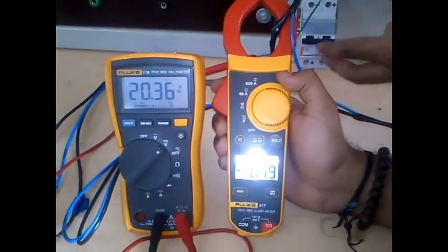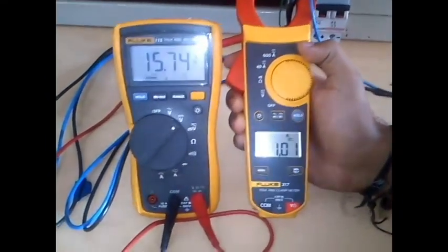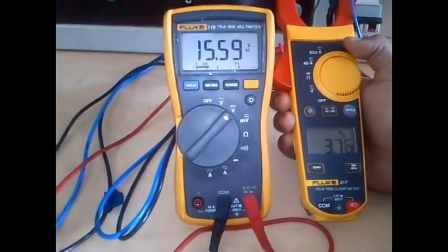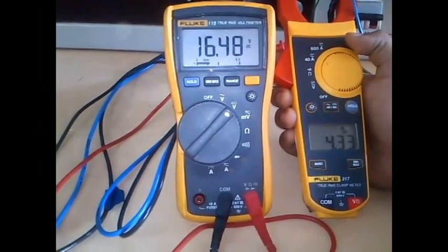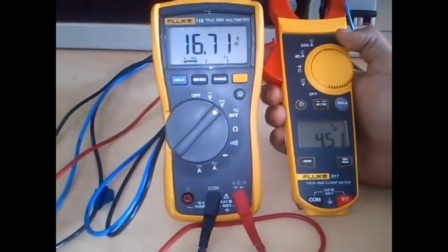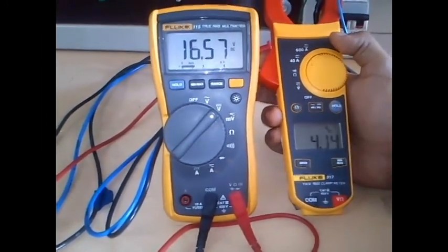Now when the switch is closed to connect the load, the voltage of the panel drops depending upon the initial duty ratio and load connected. The controller executes the MPPT algorithm in order to make the solar panel operate at maximum power. The power drawn from the solar panel is 75.6 watts.